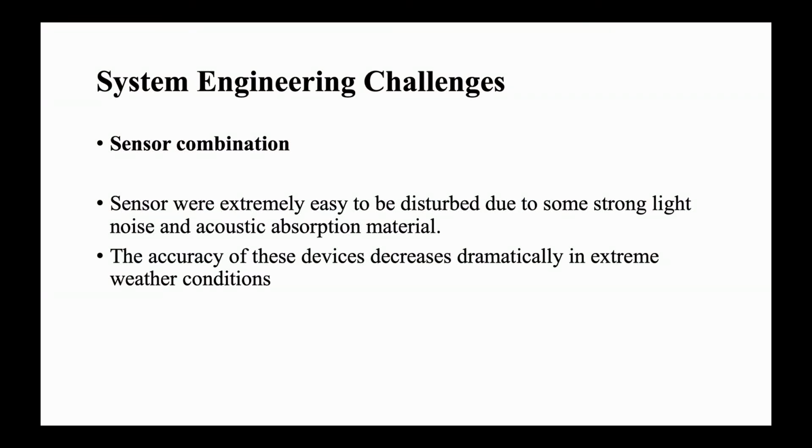of obstacles. In addition, the accuracy of these devices decreases dramatically in extreme weather conditions such as high wind, fog, rainstorm, etc. The perception effect of radar and camera is easily affected, and the recognition of traffic lights will be affected correspondingly because the color saturation is different from that in sunny days. Also, achieving efficient and rapid integration of information collected by all kinds of equipment to form a stable and intelligent system is also a big problem to be solved.